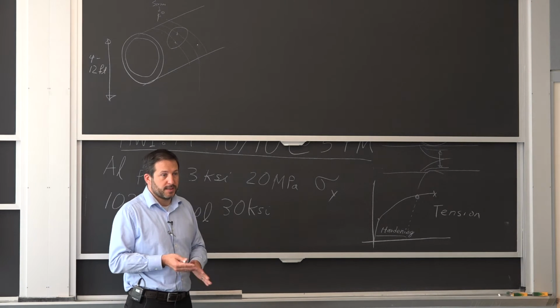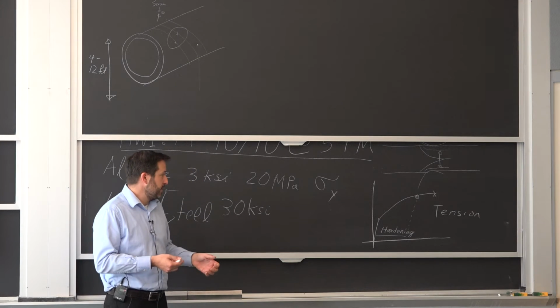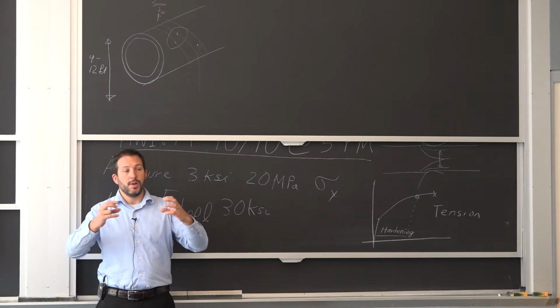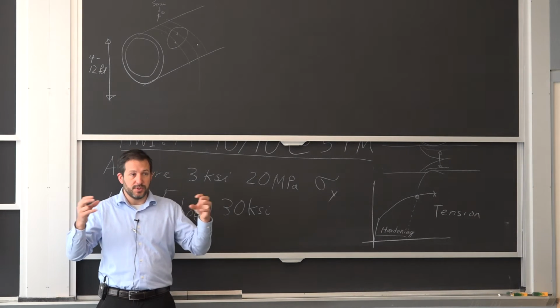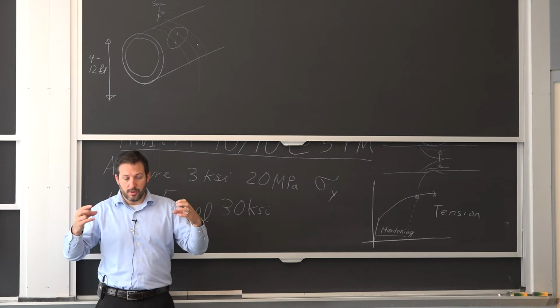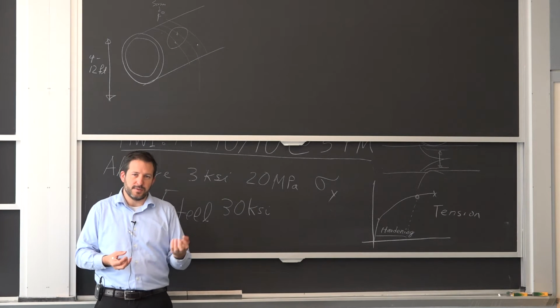So that's a little bit what you do with the steel wire. Let's say you start with a wire that's this big. If you were to pull on it, it will deform maybe 30% and then neck and break. But when you do it with all these rolls, you can get it to much smaller, so you induce a strain of, say, 200%.